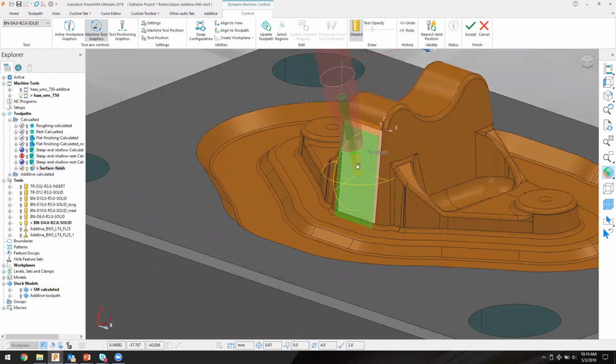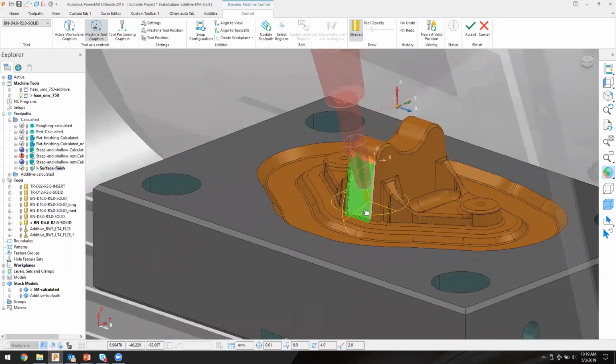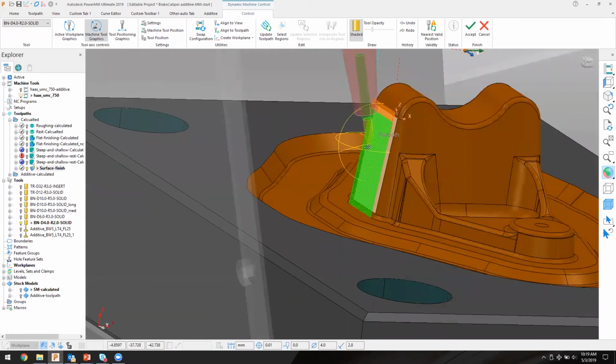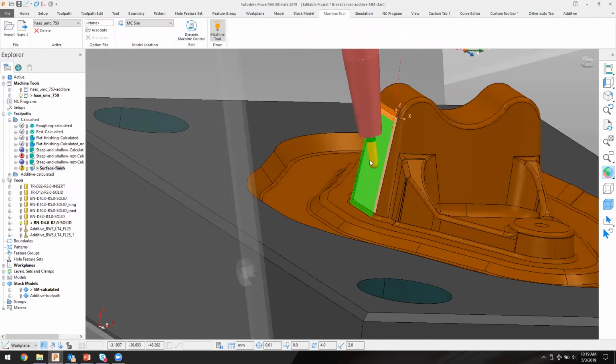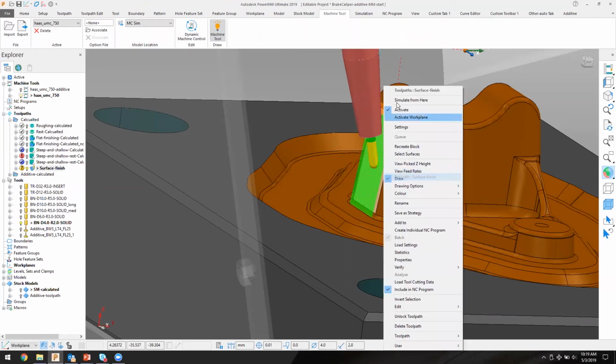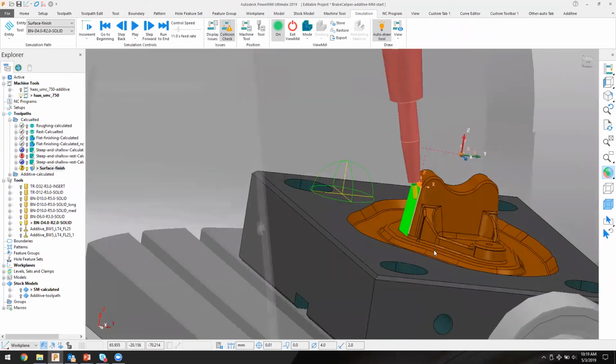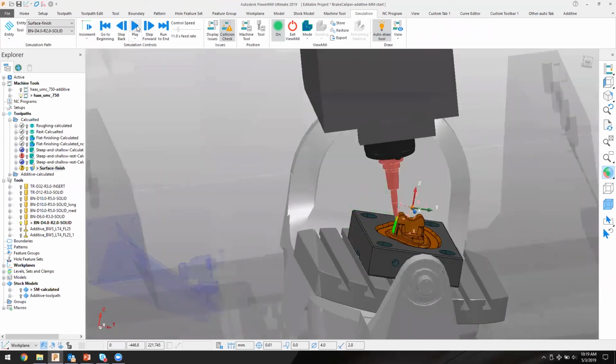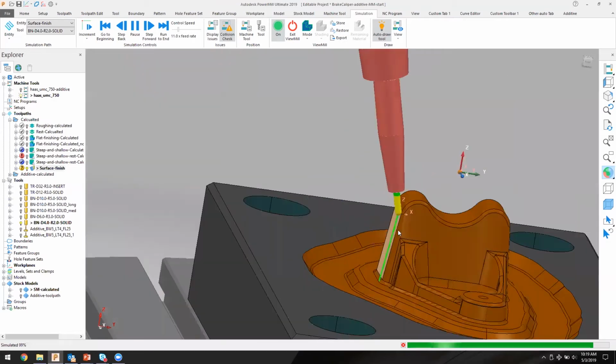So we can simply tip it and then drag our tool around on the toolpath to be able to see whether we're colliding or not over the entire area. I can then update the toolpath, and if I were to simulate that toolpath again from the start, we will see that that machine in the 5-axis positioning is able to achieve that as such.